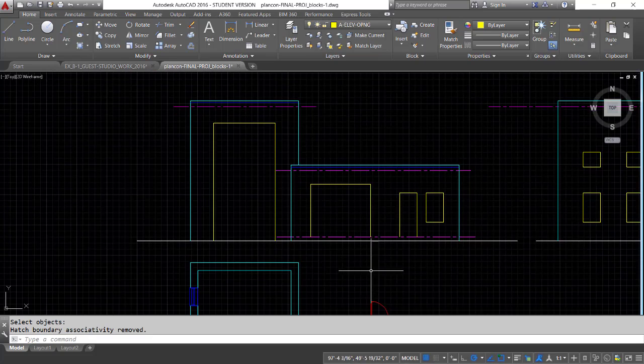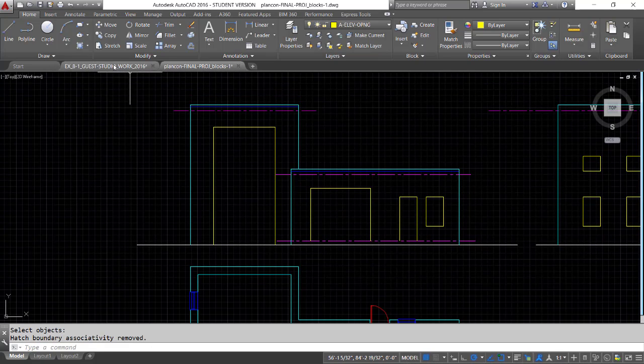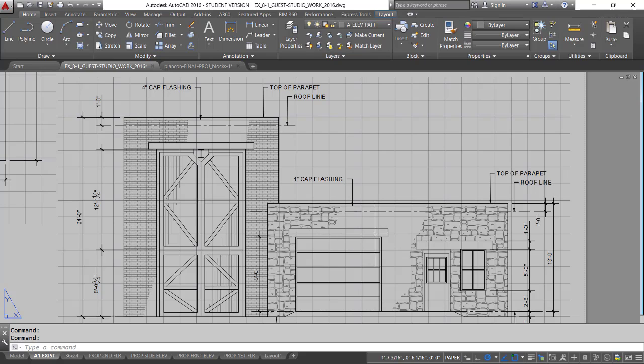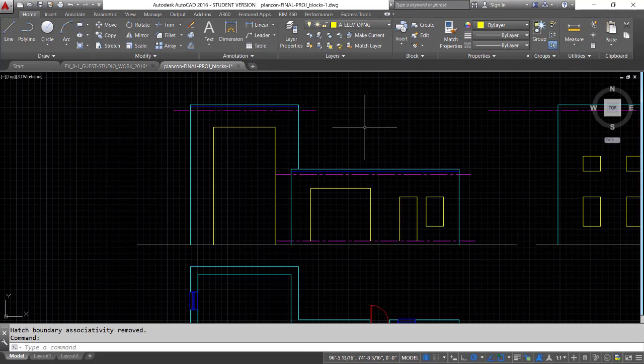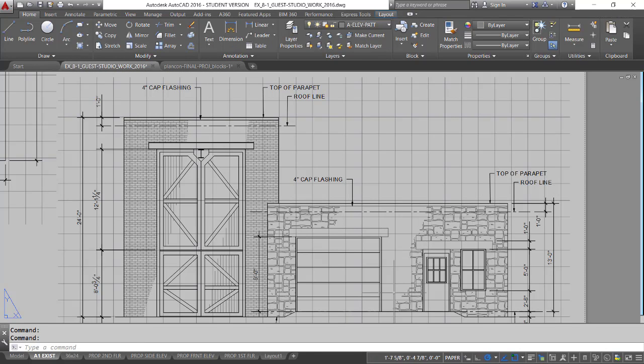Okay, so let's place some pattern on this front elevation like we saw on this one here, the front that has the lower portion and the tall portion. And you'll notice, actually, let's go back to that quickly, that the pattern doesn't fill the entire area. It doesn't fill the entire elevation all the way across, but is contained within these wavy lines. And that's a typical practice on architectural elevations, especially when they're being used for some kind of construction information, where we have things like dimensions and notes and such.